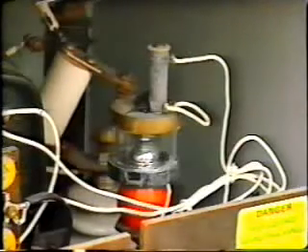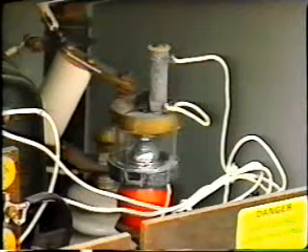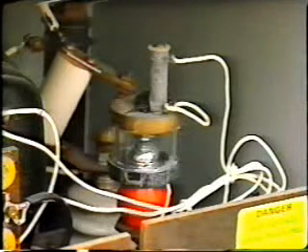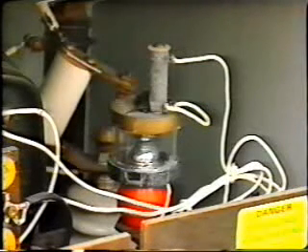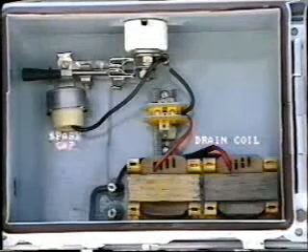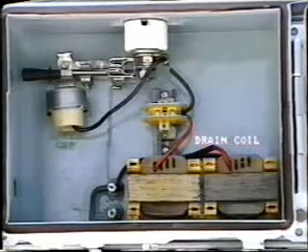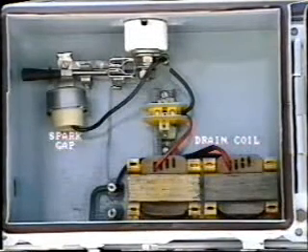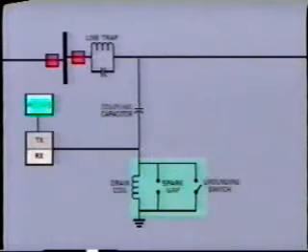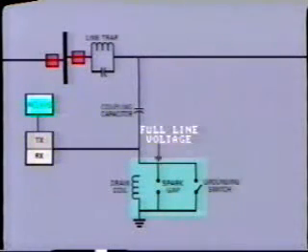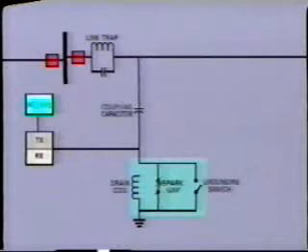It may be a gas tube protector similar to the type used on telephone circuits or on pilot wire protection. Alternatively, the lightning arrestor could consist of a simple spark gap, such as a spark plug. If the drain coil were to fail and become open-circuited, it would open the ground on the coupling capacitor. Full line voltage now appears on the protective gap. This fires and an arcing sound is produced indicating an open drain coil.